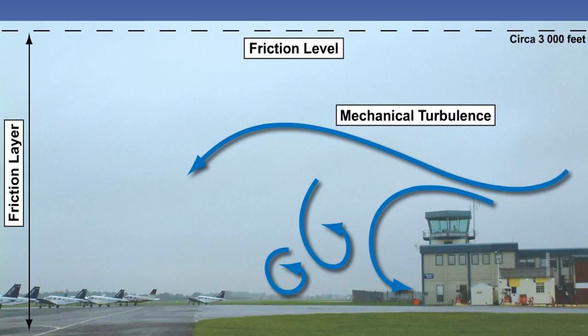To an aircraft flying at low level, topography and large buildings can have significant effects on the wind. Hills and buildings will cause mechanical turbulence, which causes gusts, but these are usually of short duration. Surface friction will also cause changes of wind speed close to the ground.